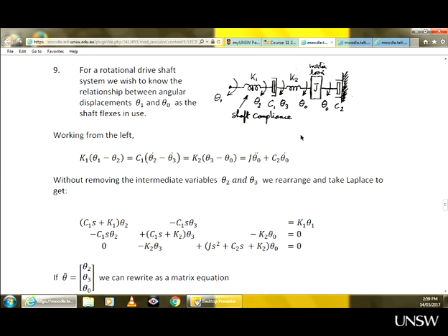Oh, so as soon as there's mass, or let me put it this way. You actually apply the torque here, and you just don't want that variable. That's not what interests us in this problem. But that torque equals K times theta 1 minus theta 2, which is the same as this torque, which is not the same as this torque because here you have inertia. Once you have inertia, the torques are not going to be the same.